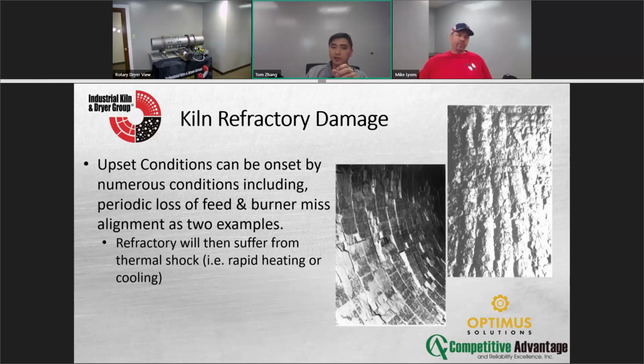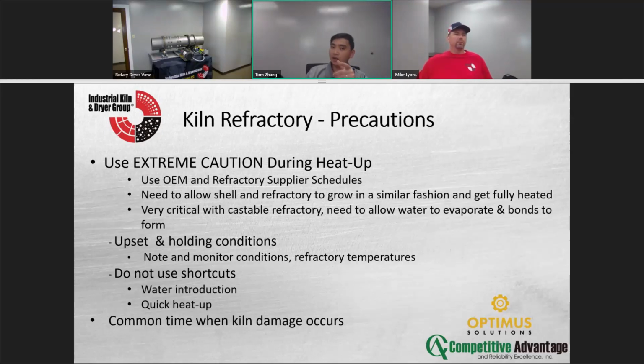And then some of these, if you get to a certain point where you need to put in castables, okay, try castables. Otherwise, on your lime kilns, your cement kilns, they call those a coating. So this is your material still building and coating on top of the kiln. So that's something that also helps on the insulation.